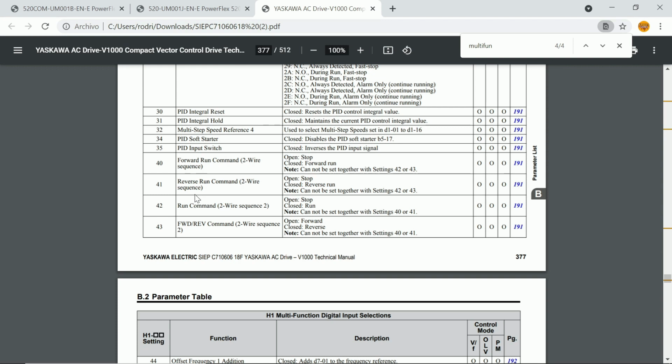But to be honest, the primary idea is their motor. We don't want to mess around with our PID. For that, you either get a temperature controller or a processor, or even easier, a PLC. So if we wish to be exact, I would not recommend PID on your drive. I've installed this, I've set it up, I've adjusted their gains manually, but guess what? It's not as efficient as a PLC PID or a temperature controller.